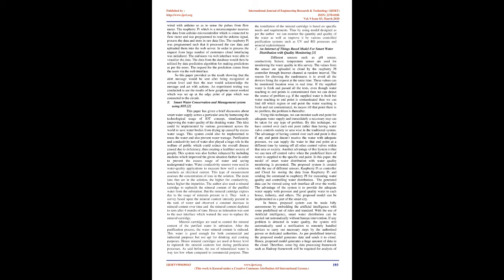The author also used a mineral cartridge to replenish the mineral content of the purified water from the substation. But the mineral cartridge expires due to the usage of the minerals present in it. They took a survey based upon the mineral content intensity present in the tank of water and observed a constant decrease in mineral content over time, and the mineral content depleted to zero after 4 months. Hence an intimation was sent to the user interface which warned the user to replace the mineral cartridge.